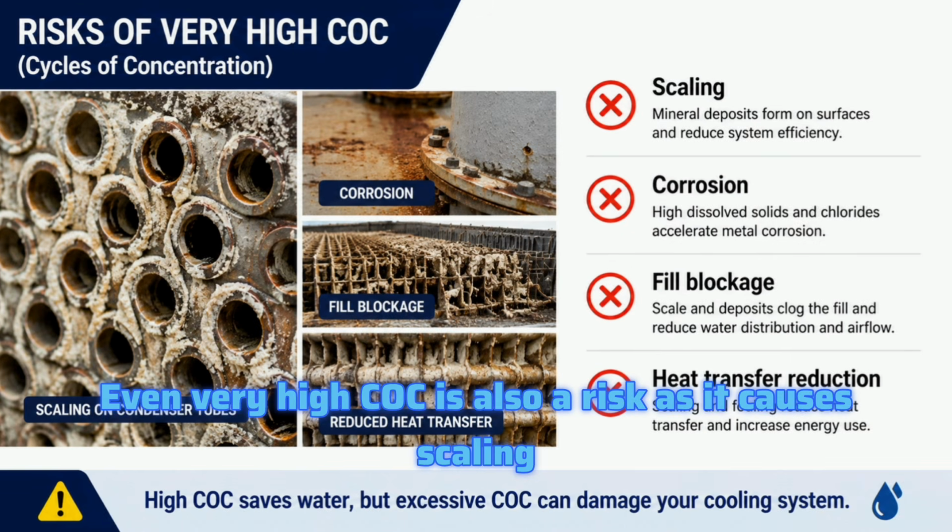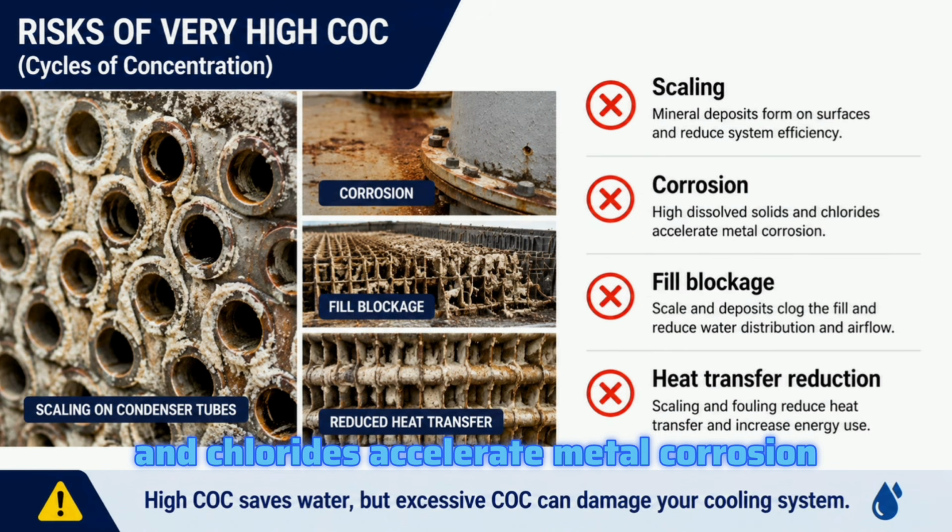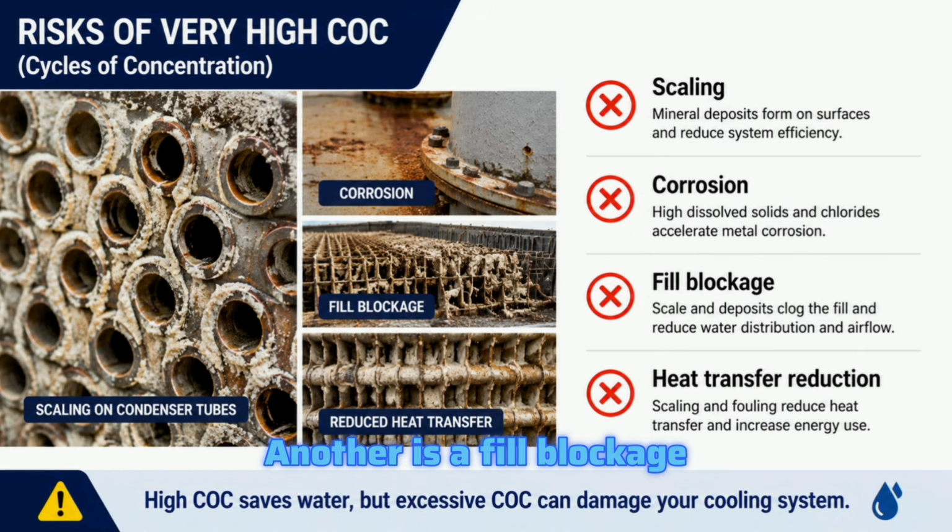Even very high COC is also a risk, as it causes scaling: mineral deposits form on surfaces and reduce system efficiency. Another is corrosion. High dissolved solids and chlorides accelerate metal corrosion. Another is fill blockage.